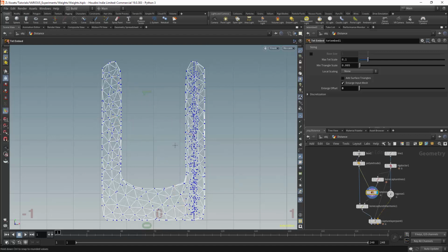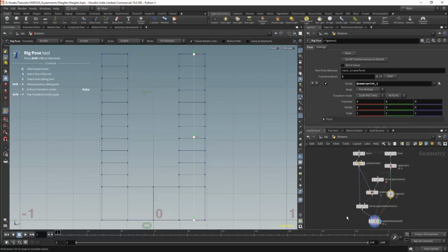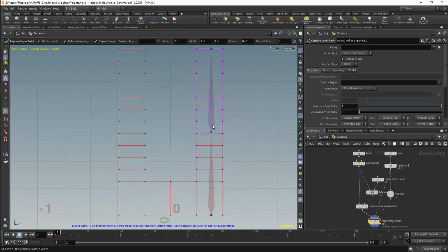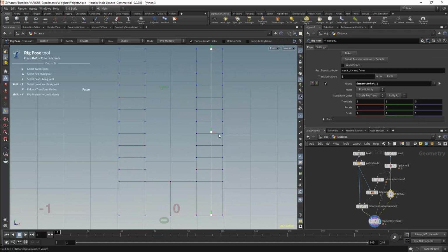Instead of calculating direct proximity, we use a series of points. Instead of calculating a direct path, we'll perform a process which is closer to joining dots. Each point will calculate the weight based on the closest point in the mesh, rather than the bone itself. This way we'll actually get to the final deformation using points that have a direct path towards the bone. The end result of this approach is that we have weights which conform properly to the geometry.